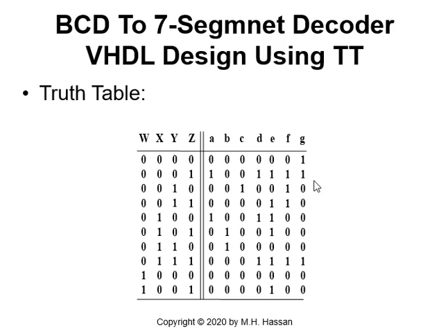And so on and so forth. Actually, for numbers 1, 2, and so on, you can check this. So this is a representation of a common anode 7-segment display. It means the anode is taken to plus 5 volt positive voltage source.